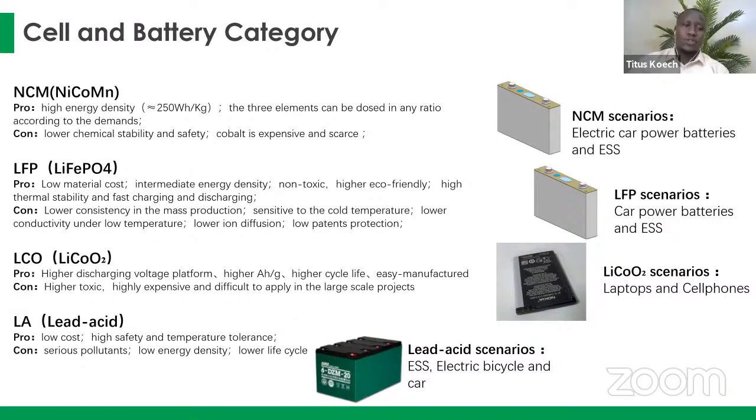The main consideration for which lithium-ion technology to use is that you look into different aspects, which include the energy density. You also look at the cost, because they will all have different costs. We will also look into the power density and the cycle life. So it all matters and it's all different. Now, we can have applications from electric vehicles, cell phones, and power drills, and also energy storage solutions for solar PV and other applications as well.